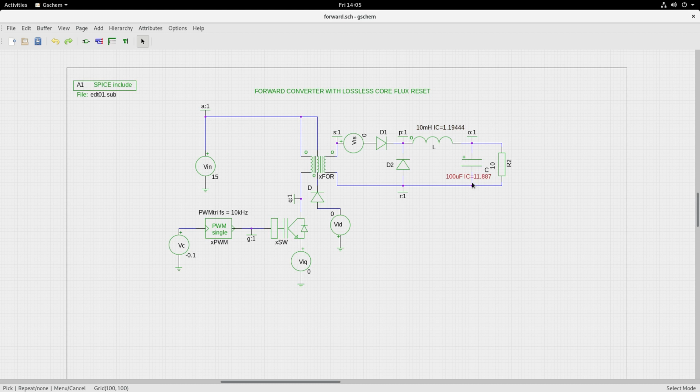These two are the states of the system, and therefore you need to provide initial conditions for these two states. I have given a voltage initial condition value here, again taken from the steady state value of the previous simulation that I did without initial conditions. By giving this initial condition, the simulation can be very quick, and you can directly look at the steady state and see the simulation for just a few cycles, 5 or 6 cycles.